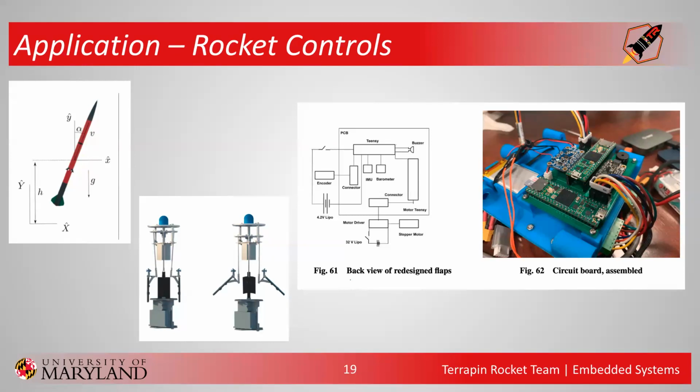It's actually a very complicated algorithm, but simply what it does is it reads the state of the rocket. We have two sensors, an accelerometer, which reads our acceleration, and a barometer, which reads our height above the ground. We use this data; you can integrate it and do all this stuff. The fancy term is an unscented Kalman filter that we use, but you don't need to know that. It basically integrates the data and uses a math model to figure out what our apogee is, and then tells another controller what angle to deploy the motor's flap angle at.